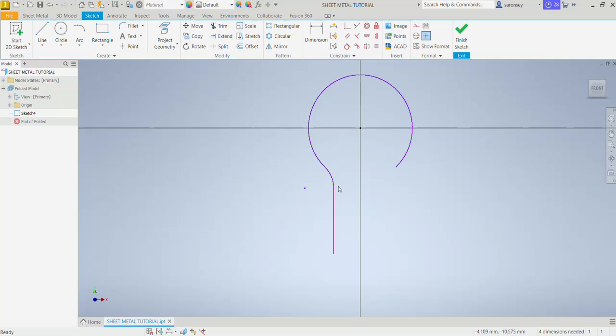We want to create this arc and this line on this other side as well. But there's no need going through the process of drawing again. So we'll take advantage of our mirror command. But before that, let's create the line we want to mirror about. So we can use a constructional line for this purpose. Select the line command.